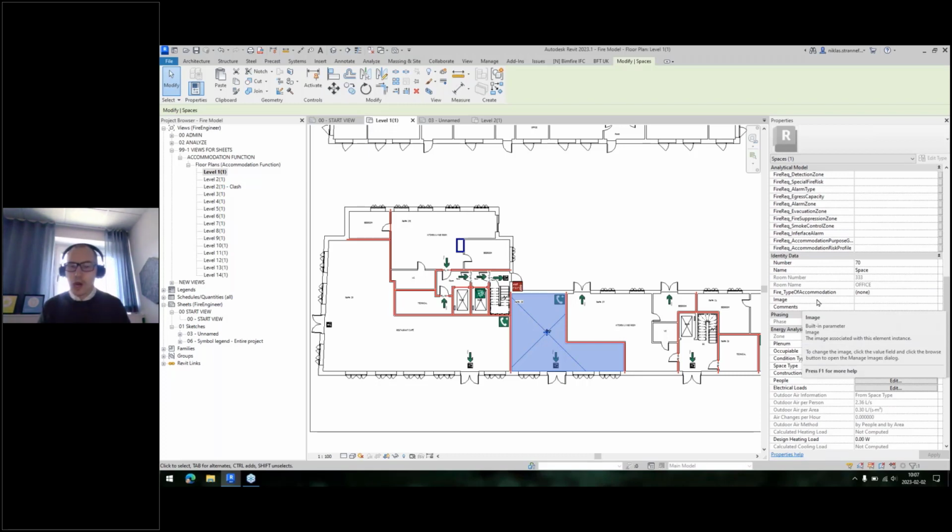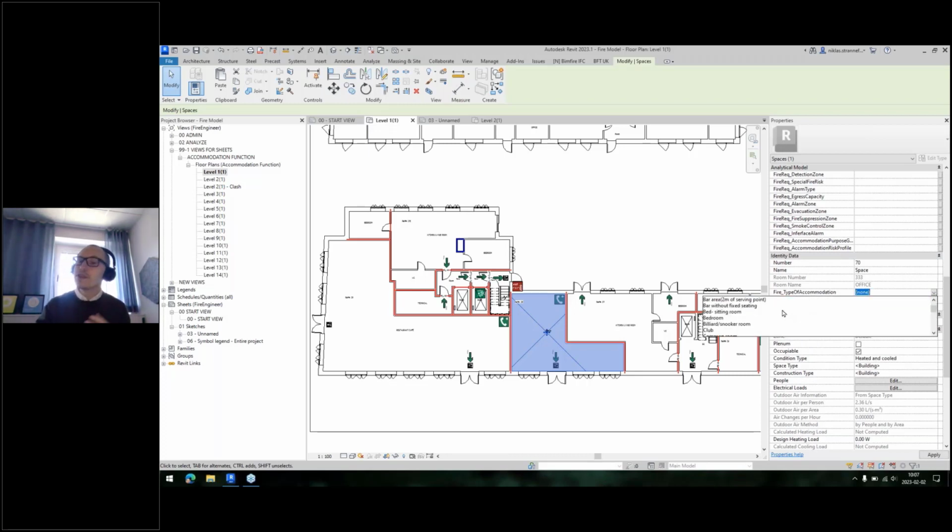For now, we only have had the time to prepare this key schedule with the correct values in the UK and the Swedish one. And we're going to add, of course, the other countries as well, coming up in the next release. What this does is basically we can define what type of accommodation it is, and that will change the floor spacing requirement. Meaning, we can see here there's a drop down, and if we don't want to add the occupancy load factor manually, we can choose what kind of accommodation, and that will automatically assign the occupancy load factor or floor space factor.